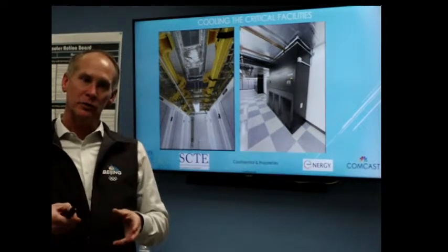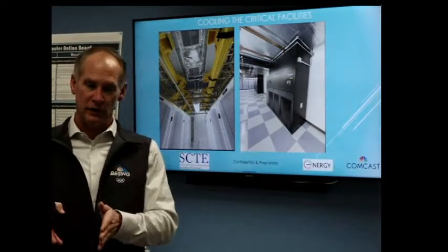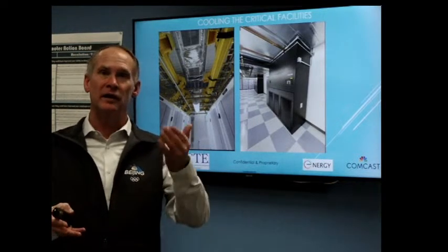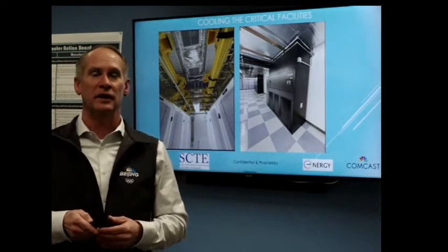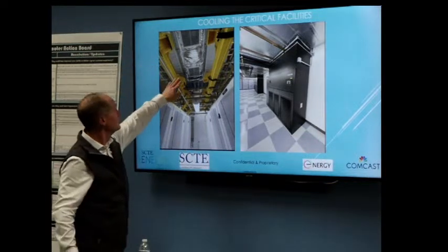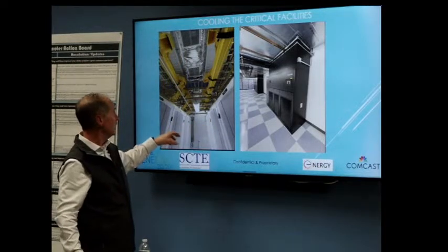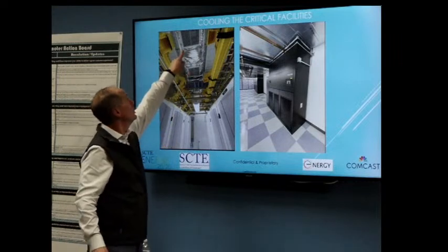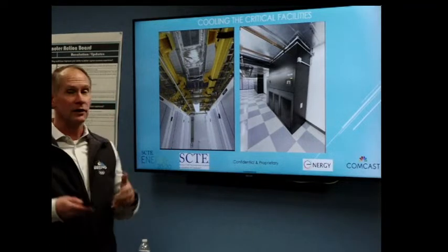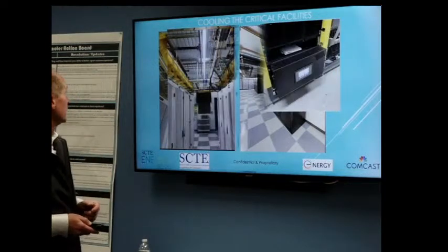Whenever you add a new piece of load, or as a critical infrastructure engineer, you approve a new piece of load, you have to understand that there's a correlating BTU value, British thermal unit, that is really going to drive additional airflow and an additional tonnage calculation. So we, being critical infrastructure professionals, need to be able to analyze what your ductwork is capable of providing, what the equipment consumption is, and what the new equipment consumption is, and that you can accurately and availably provide cooling to your space in a resilient manner. So that's another means of cooling systems.